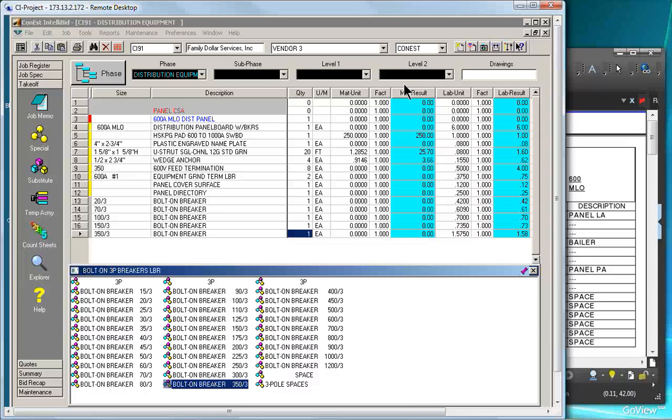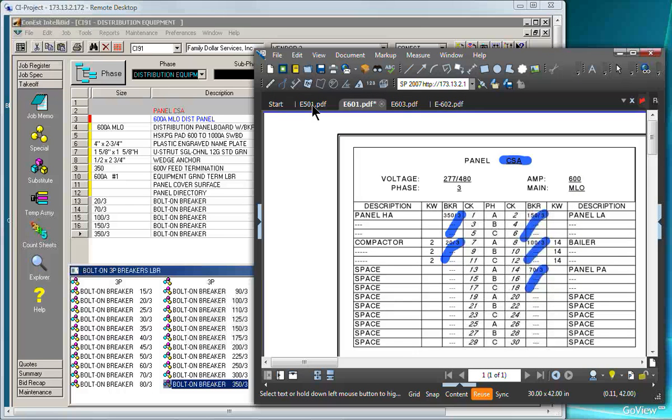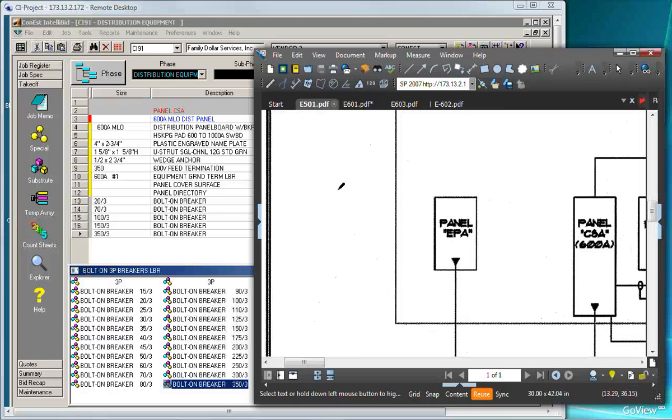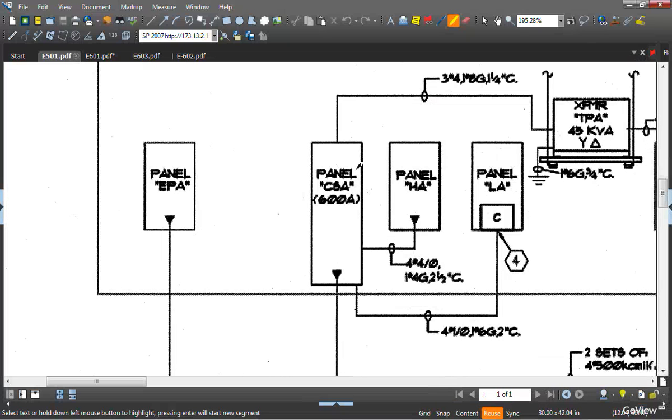Now, or actually we didn't quite finish it, I'm going to go over to our riser diagram. I'm going to zoom in on our schedule. Okay, there it is, and simply do the same thing. I'm going to put a nice mark through it, keep it clean. You can just mark the CSA, whatever it is, to make it nice so everybody knows that we've taken off all the panel boards. This would be a double check to, you know, sometimes the panel descriptions are not on the plans, but they show up on the riser. So it's our cross-check method.